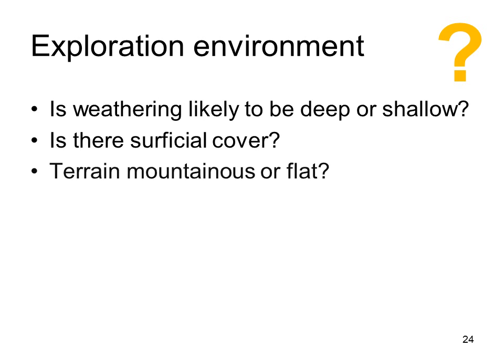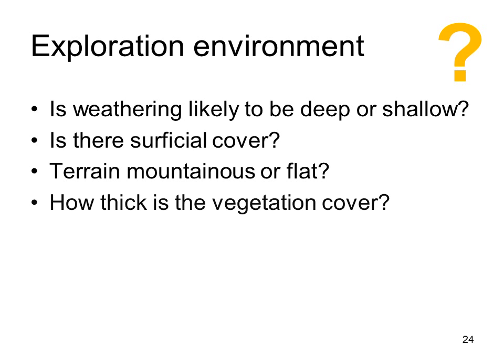Is the terrain mountainous or flat? For example, a big gravity survey is impractical in a mountainous terrain, and rough topography will also limit airborne surveys in fixed-wing aircraft, and it may be necessary to switch to a helicopter-borne method. How thick is the vegetation cover? Thick tree canopies can mask infrared spectrometer surveys, and thick mulch in tropical forests can make soil sampling very difficult or impossible.